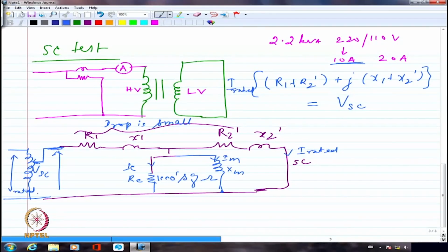From there is a variac or auto transformer. From the auto transformer, this is the variable jockey point which is probably put at the very minimum number of turns. So what I will do is slowly increase the applied voltage by increasing the jockey position of the transformer, or rotate it. I have to rotate it and then make sure that I don't exceed the rated current. So I can't really directly apply this here. So let me show this here again.